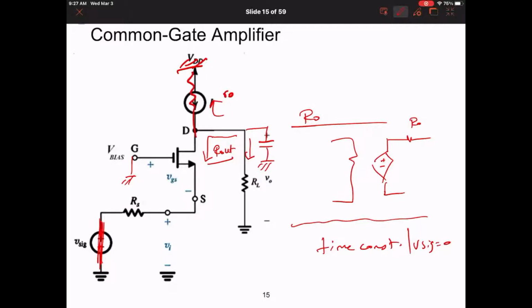Okay, so the name R out is just for terminology, to say I'm looking at this amplifier and setting its Vsig to 0. Is this clear? Okay, but you know which resistance to set. If I'm calculating RO, I set Vn to 0, and Vn is right at the end of Rsig.